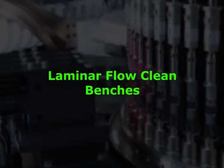In horizontal laminar flow clean benches, there is a slightly reduced level of turbulence compared to the vertical flow clean benches due to the airflow not striking the work surface. However, vertical laminar flow clean benches generate less turbulence around large pieces of equipment as compared to the horizontal laminar flow clean benches.